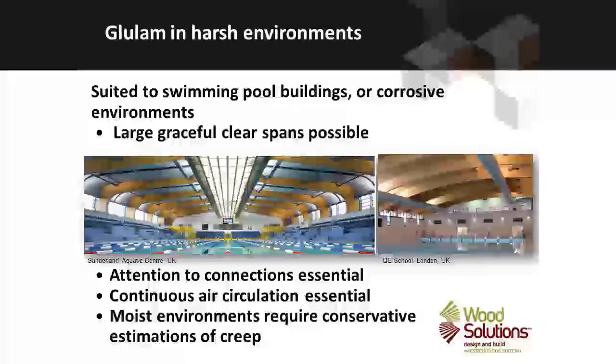Glulam can be used in harsh environments, and when used in a harsh environment where moisture content is going to change significantly, we need to pay particular attention to connections, that they don't trap moisture, that they don't expose steel elements to the potential of corrosion. We need to also look at continuous air circulation so that the air is moving around the timber at all time, and require also conservative estimates of creep, because the moisture movements may accentuate the creep that timber is exposed to under long duration loads.